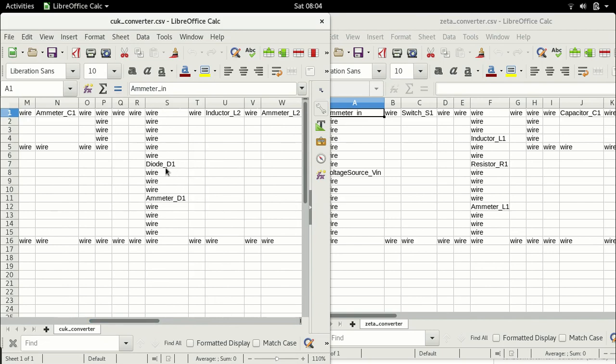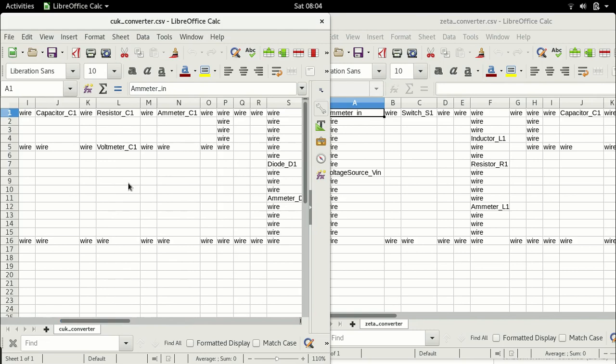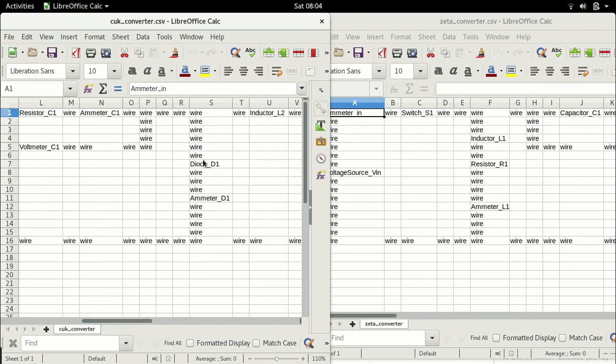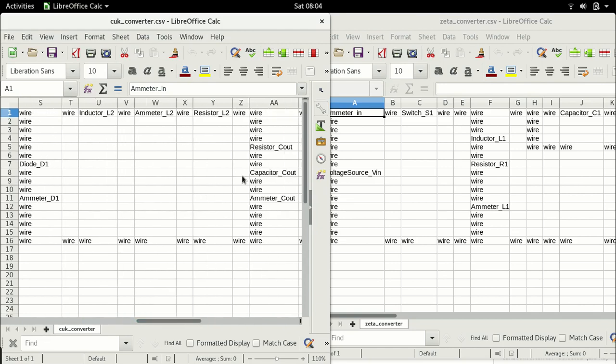Remember, the diode does not conduct because the current through the diode has to flow downwards, and since in this case the current is trying to flow upwards, because remember the capacitor is discharging in the counterclockwise direction, which means the current will have to flow upwards, which is not possible, right? This diode conducts downwards. So in this case, the inductor is charging and the output capacitor is being fed from this decoupling capacitor.